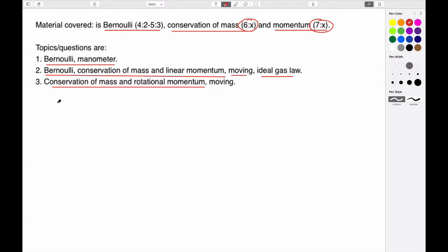But in terms of what you need to know, you need the equation of state. And that is the ideal gas law, which relates pressures to densities, gas constant, and temperature. Temperature and pressures have to be absolute, as you know, and the gas constant is something that usually you're given rather than required to bring, and it's different for each individual gas rather than the ideal gas constant.